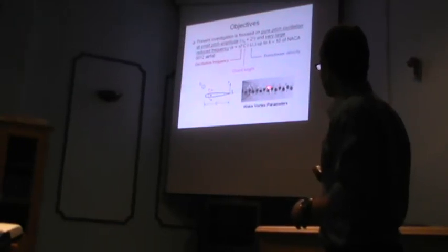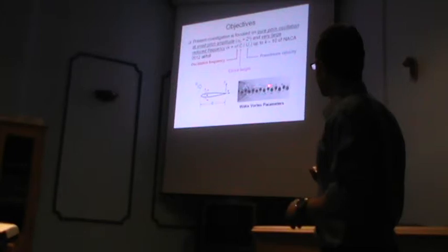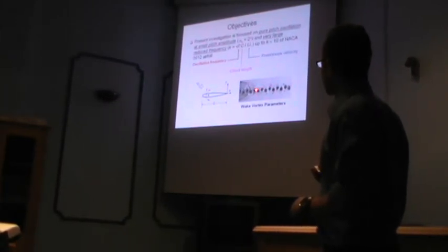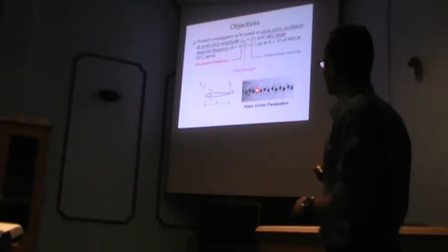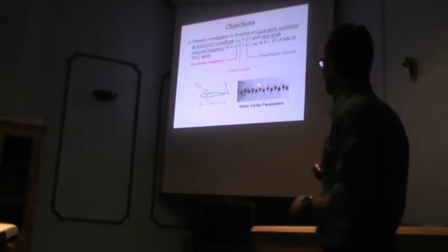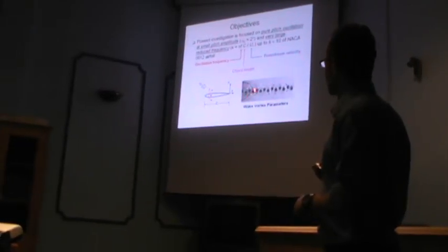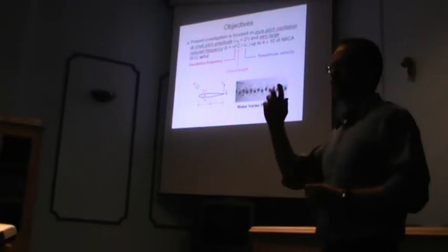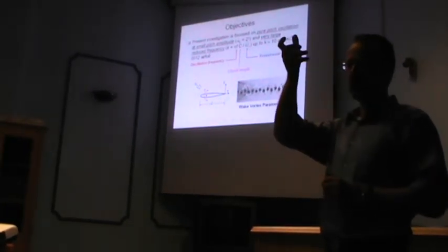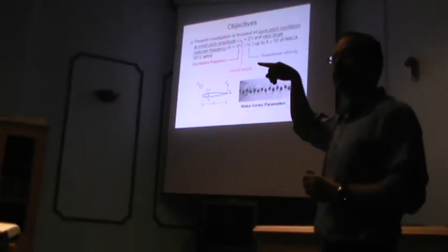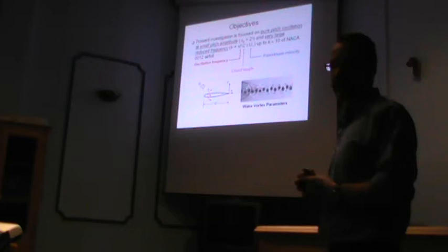But if we take the 2 vortices with different sense of rotation, the spacing in the cross-flow direction or y direction between their centers, we will call it D. The spacing in the streamwise direction between a vortex and another one with a similar sign, we call it A. The circulation of the vortex, which is an indication of the strength of the swirl that the vortex produces, is gamma. And plus will be in the counterclockwise direction, and negative will be in the clockwise direction.